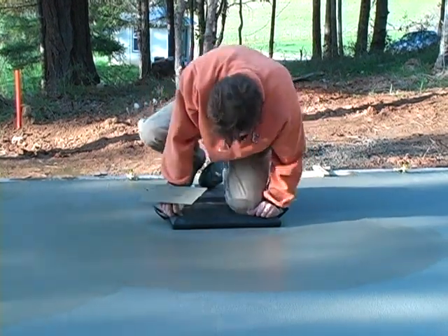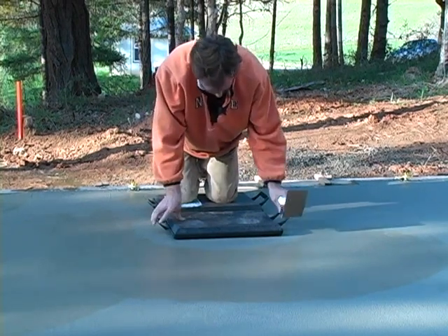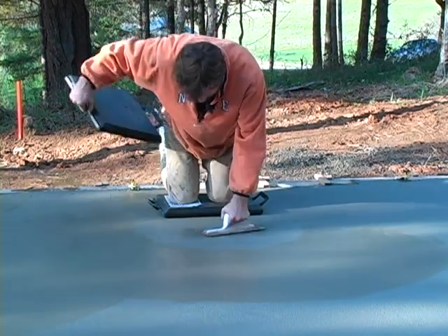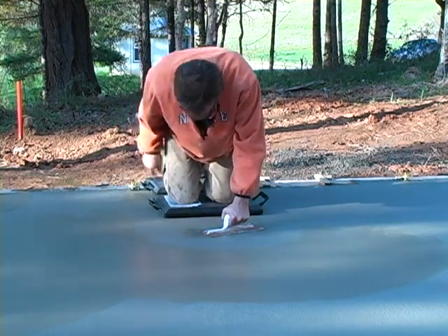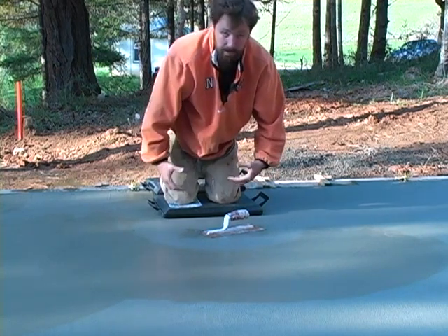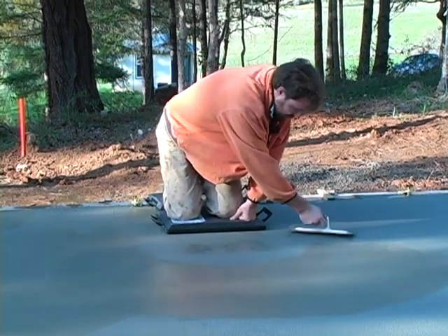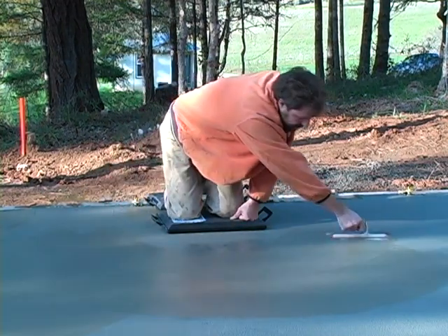And then to move back, I just step onto my rear knee board here, move this one behind me. I can use my trowel to lean on. Then I got my feet on there. It keeps my feet. Otherwise, if I just use one, I have a tendency to want to put my feet down, and I can't reach out as far onto the slab because I've only got one to work with.